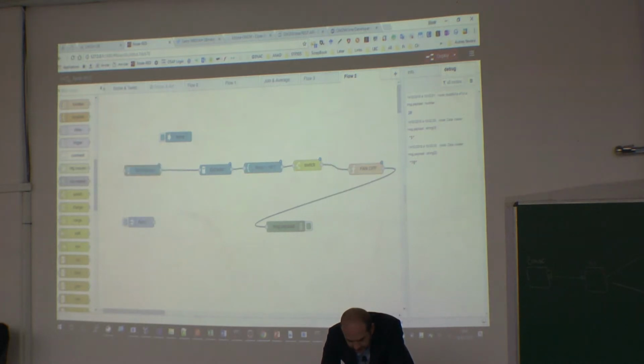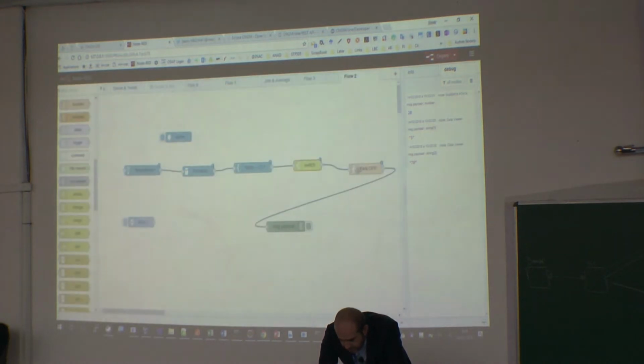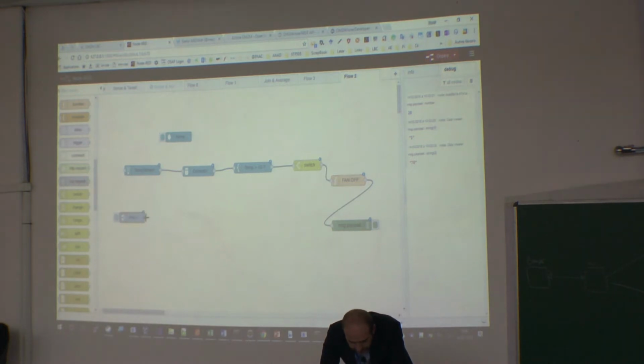So the flow is something like this. We extract the value of the temperature sensor. We then look into the interesting value inside the response. Test this value against a threshold. Here I set 10. And if this condition is true, I will trigger the command of putting the fan off, in the state off. And I will show the result here. Again, I need to do this to launch my flow.